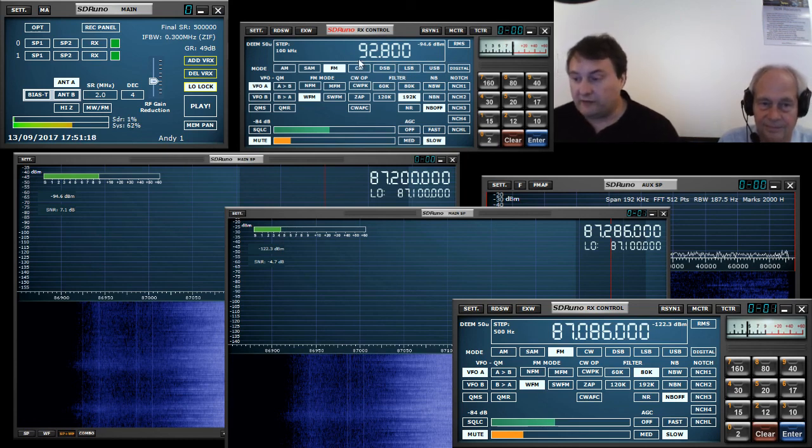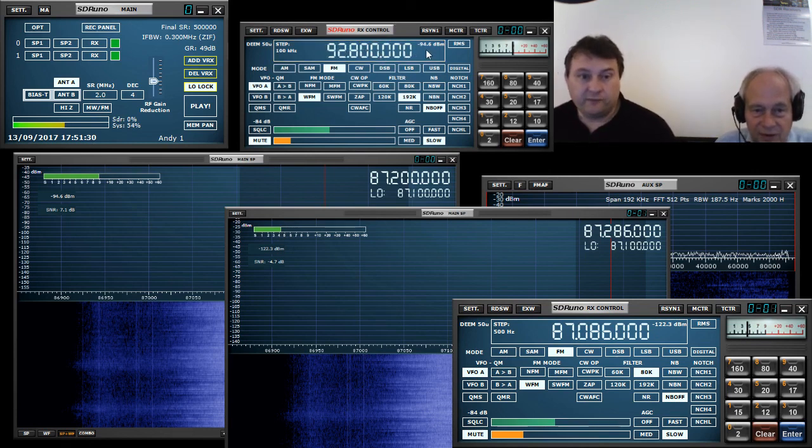In fact, what they've actually specified there is 92.8 kilohertz. So it's 92800, return. And the frequency isn't locked in until I press return and the box turns back to white. If the box is still green, it means that you're still in frequency input mode, and that won't be reflected in the software.